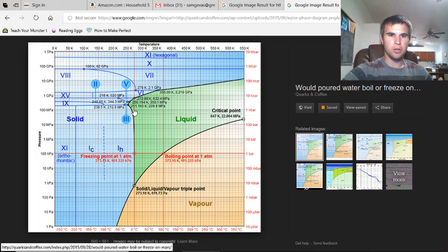until you increase significantly in pressure, and then it gets stupid. We don't deal with that, so we don't care. We're all about down here. The triple point is called the triple point because that is a single pressure and temperature at which water can exist as a liquid, a solid, and a vapor. But what we're interested in is that if you go below the triple point, liquid is no longer possible, and the phase change for water can happen immediately from solid to vapor.